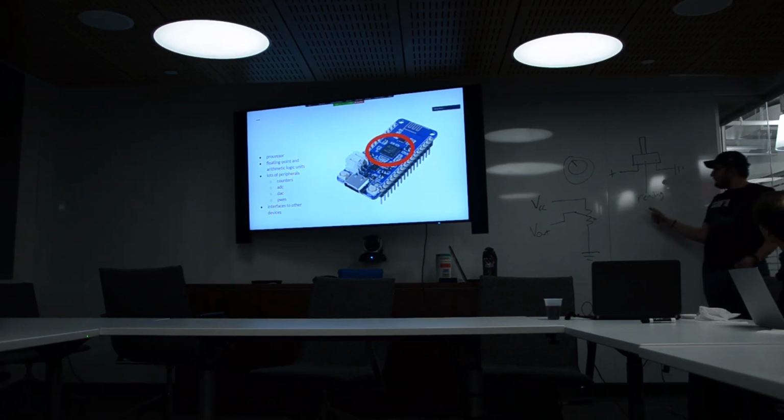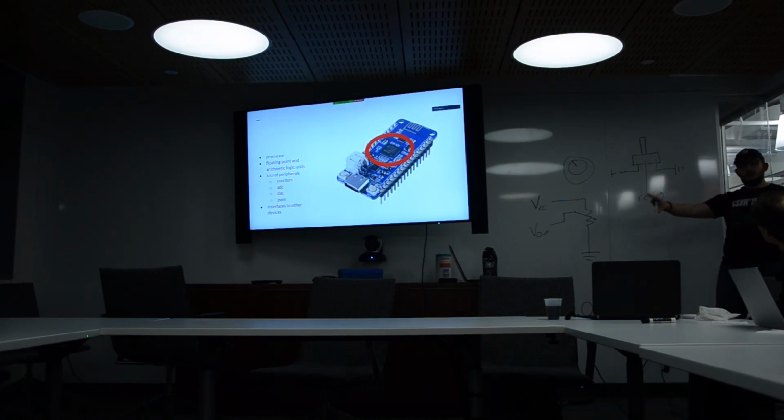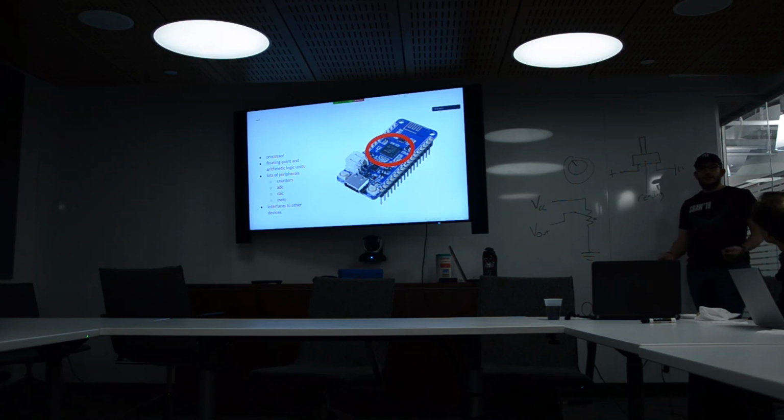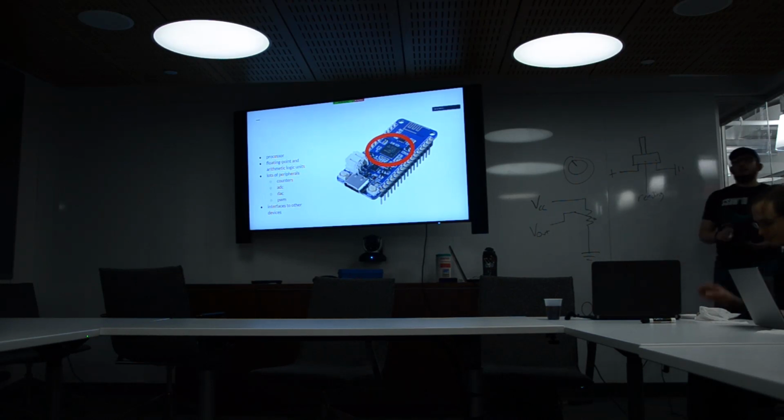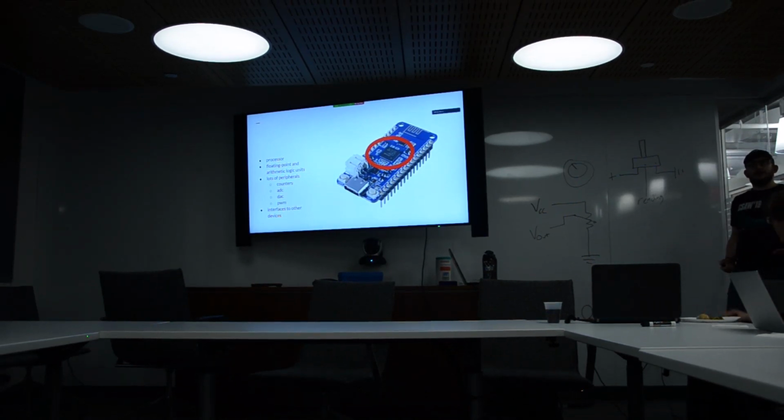So you take this value and you connect it to your analog to digital converter, which is a peripheral on your microcontroller, and it can tell you what the voltage is at the wiper. Then you read the data sheet for the part that you bought, because it's all based on what parts you buy, different values. That can tell you what real world value that signifies.